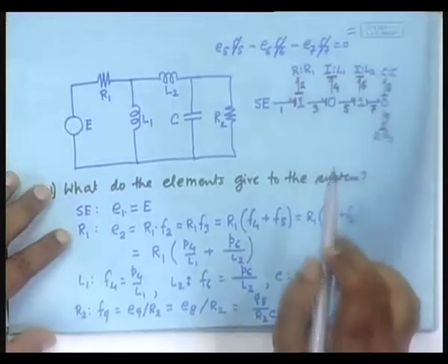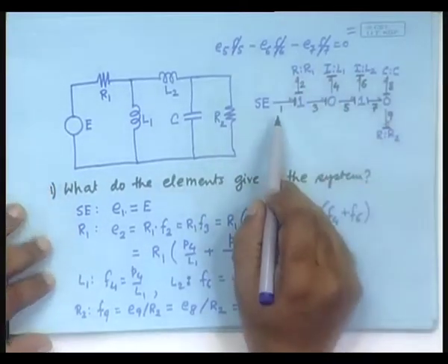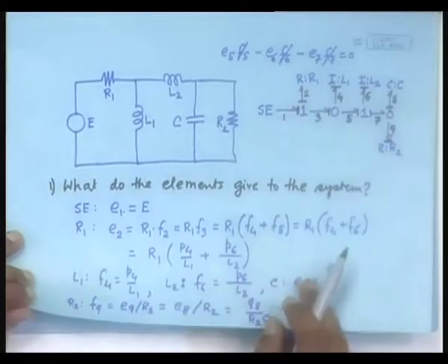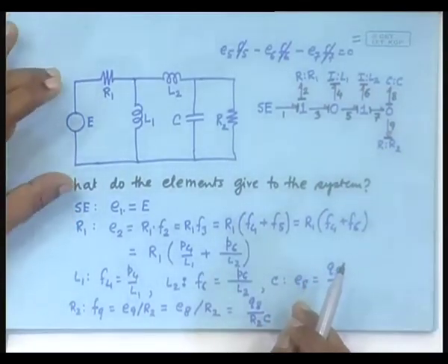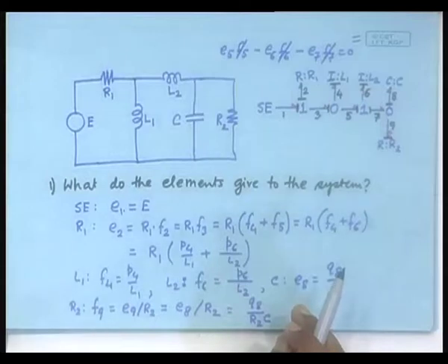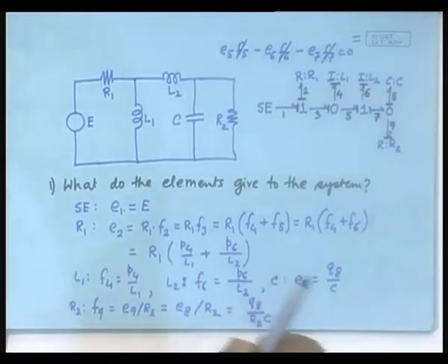The blind procedure is something like this. Say if we take this circuit, we had obtained this bond graph by simply working by logic. Now, in this case the procedure, which is somewhat algorithmic, will be to identify the points that can be at different voltages, what are called the nodes. So, what are the nodes here?